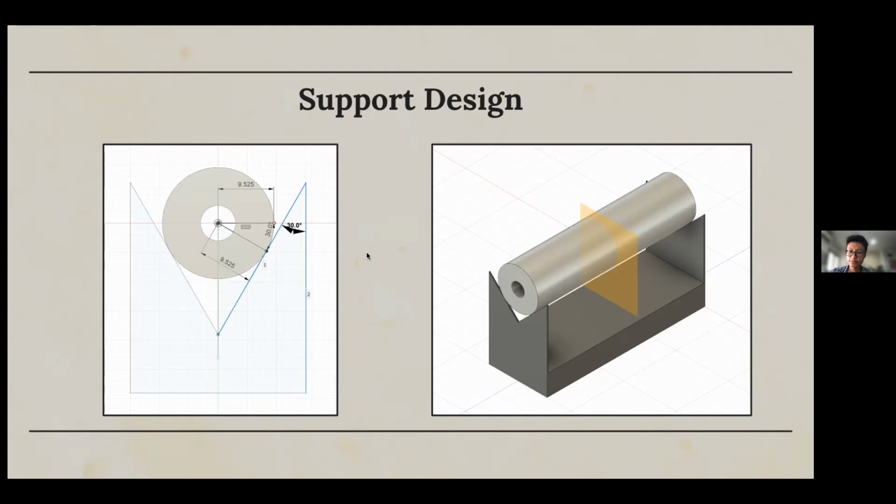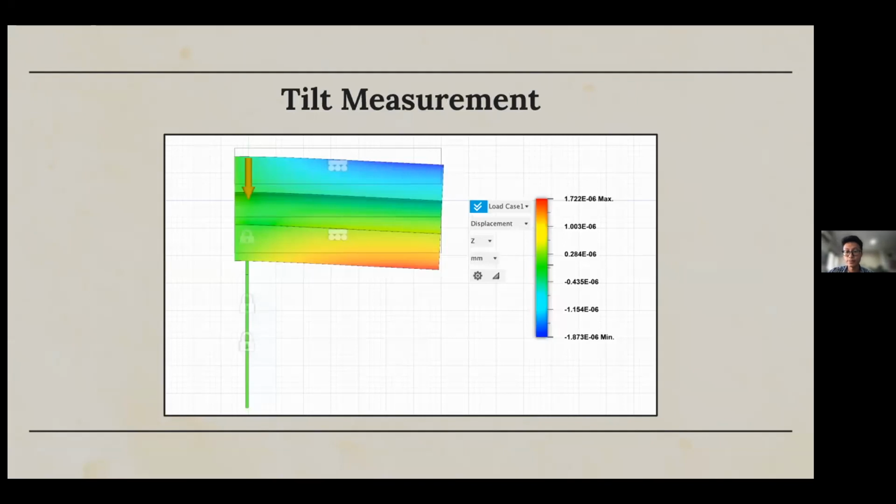For each of the selected angles, the position of the groove will be adjusted and the displacement will be measured from the edge of the cavity to the support. Now, since the support has a thickness, the measured displacement will be in the middle of the support, which includes half of the support thickness. Depending on the setup of the cavity support model, the edges of the cavity will either tilt inwards or outwards. The study aims to ensure that there's minimal tilt along the edges of the cavity.